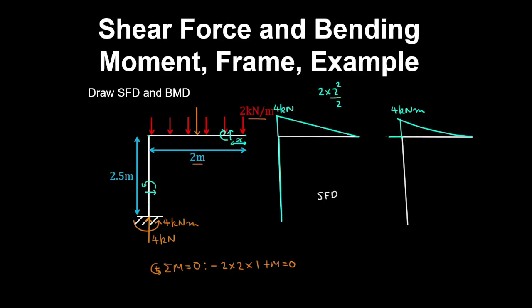And that has the same magnitude as the bending moment in the column, because there's no externally applied moment at the joint. And we can see that there's no horizontal reaction acting on this segment, so the bending moment is going to be constant throughout that column. And at the support it is going to be equal to the moment reaction.